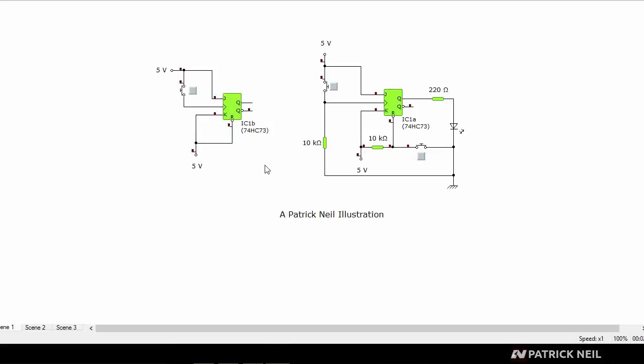Now, a flip-flop, as mentioned earlier, is a circuit that whenever it receives a sequence of voltage on the input, either from low to high or high to low, will change the output to a state, and it latches that output in that state. Until you make that same signal again, the output will then switch back to the previous state. It's better for me to experiment to reinforce what I just said. For example, this circuit right now, this pin is low. Whenever I push this button, it will go high. Just like that.